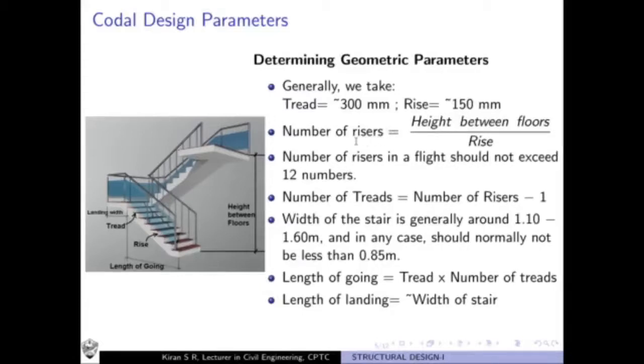Now coming to the number of risers, you need to determine the number of risers in the entire staircase, and you may be given in the question the height between the floors. By height between the floors, please keep in mind that it is the surface to surface height.